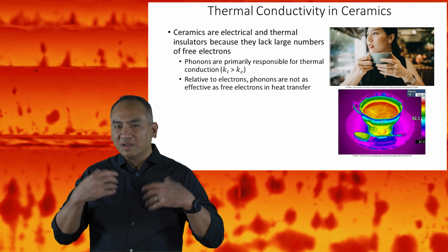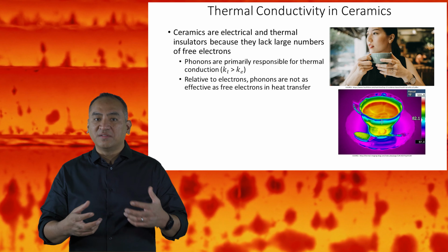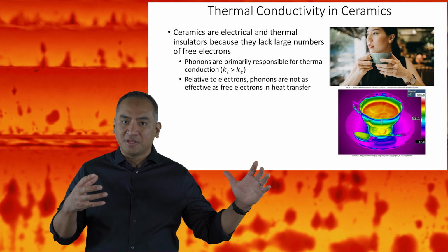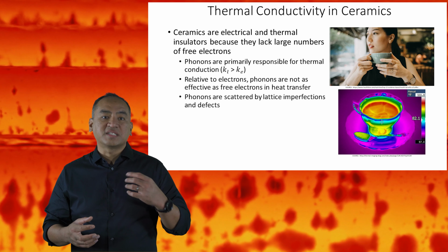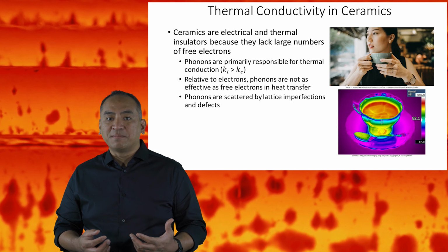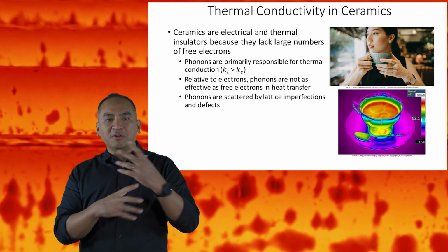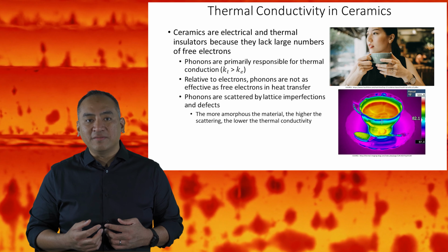However, relative to electrons, phonons are not as effective as free electrons when it comes to transferring heat energy. Furthermore, we just discussed how phonons are scattered by lattice imperfections and defects. The more amorphous a material, the higher the scattering, the lower the thermal conductivity.